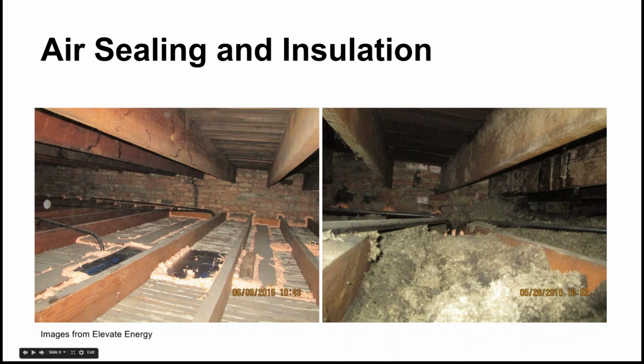Then the other part of this I want to talk about is insulation. With insulation, you're reducing all three forms of heat transfer. You're reducing radiation and convection within empty cavities, like within the wall or the attic, and then you're also forcing heat to conduct through foams or fibers or pockets of air, and those are all poor conductors compared to a slab of wood or metal or anything like that.